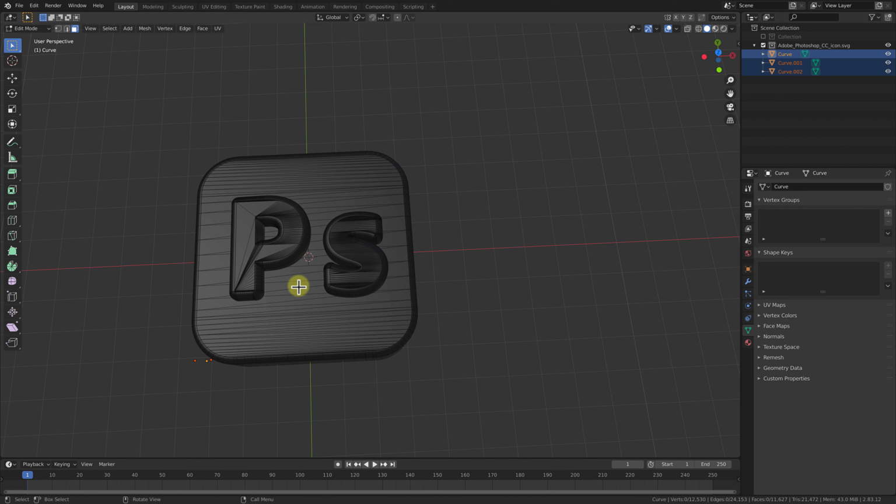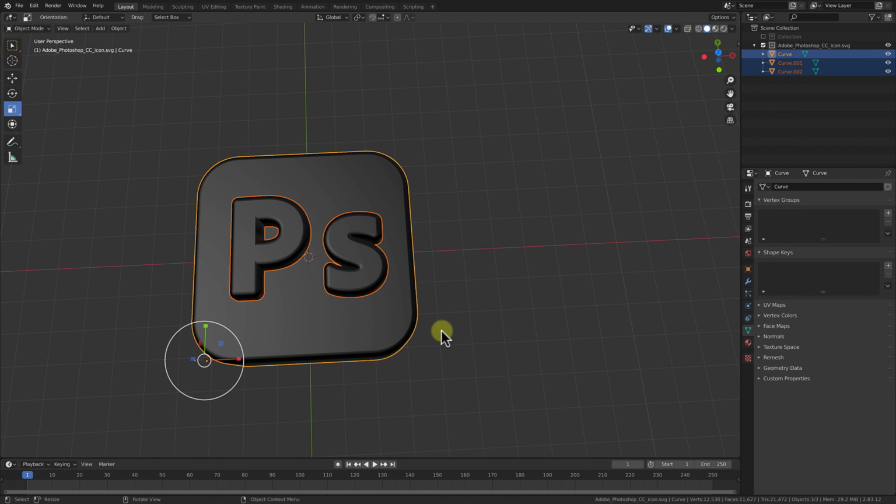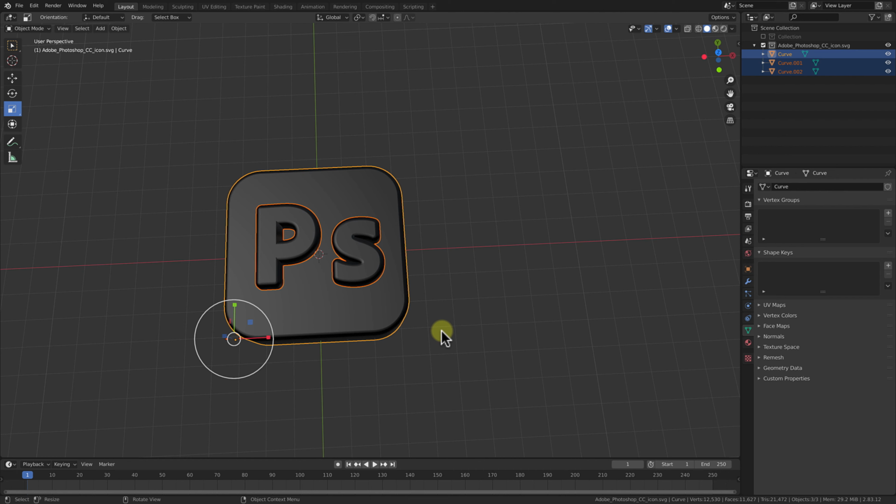So usually you want to do some cleanup of these meshes if we want to continue to edit them, or use these objects for animations or things. So usually these SVG-turned-3D objects are not great for doing animations, nor good for exporting for 3D printing. However, if you're just doing a 3D illustration, going to do a still 3D photo, then it doesn't matter. And it's such an easy and quick way to turn a 2D design into a 3D object. Basically following these steps, you can turn almost any SVG file into a 3D object very easily.